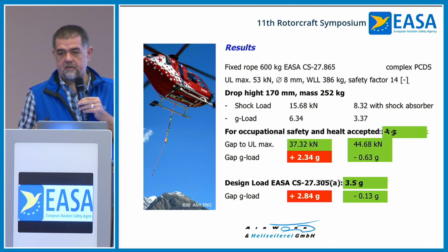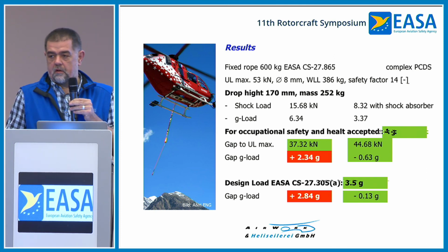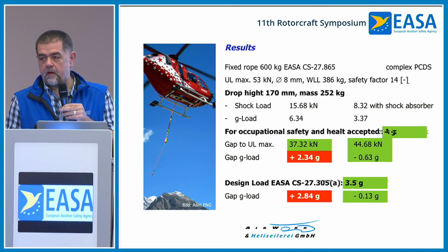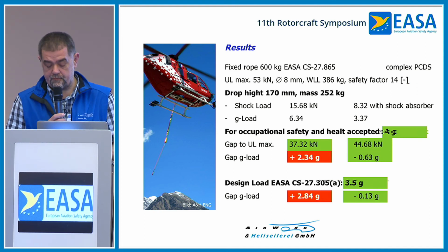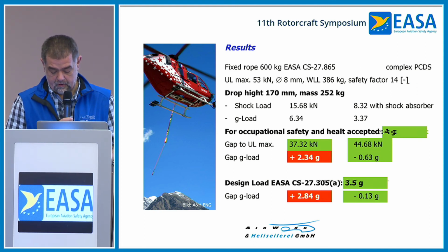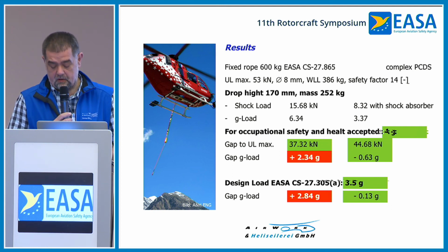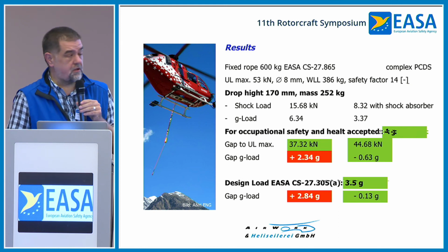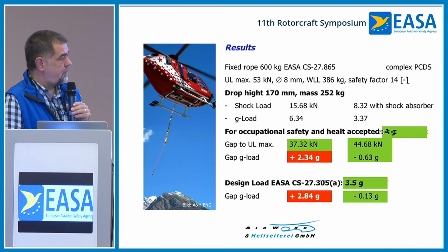During the EASA certification for a 600 kilogram fixed rope system for H135, we tested also with 600 kilograms, and we have a G-load with damper from 3G.